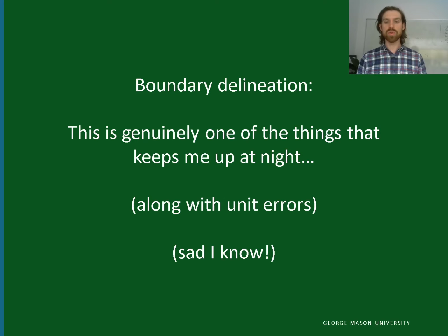You have to be aware of what the unit is, but also you need to be cognizant of the way that you design the model. And here I'm talking specifically about the zoning boundary issues. So if you use different sized boundaries, or you place the boundaries in different places, then you may well get a different answer.